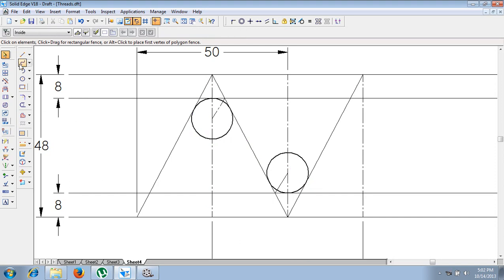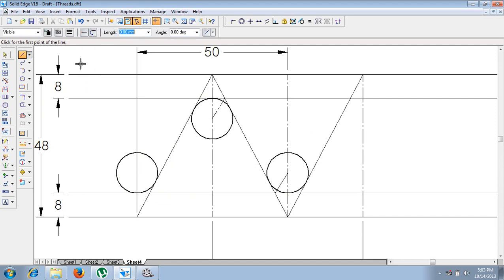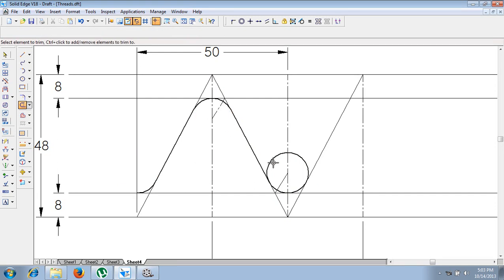dimensions. Now before using the line command, using the move command, just copy this circle, and this circle should be placed at a 50 mm distance over here. Now using a line command with 0.5 mm as a thickness, start a line like this, which is supposed to be tangential and it should be connected like this. In the same fashion, from here to here, we just draw a line. Now using a trim command, let us trim the unwanted portions of our circles.